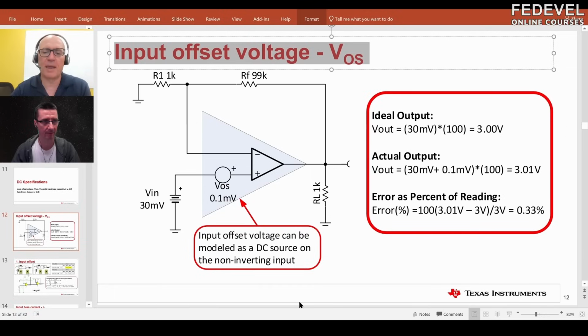So you might have multiple amplifiers, and the analog to digital converter itself will have an offset. The amplifiers will have an offset. We'll see that bias current can generate an offset, and all those errors will lump together. In your microcontroller, you can apply a test signal of 0 volts in, and then maybe your full scale signal in, and then you go through a calibration where you mathematically correct for that.